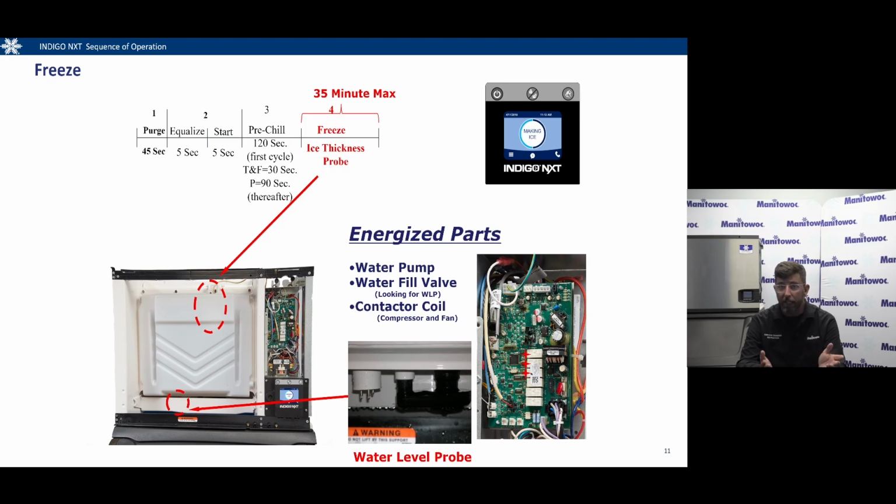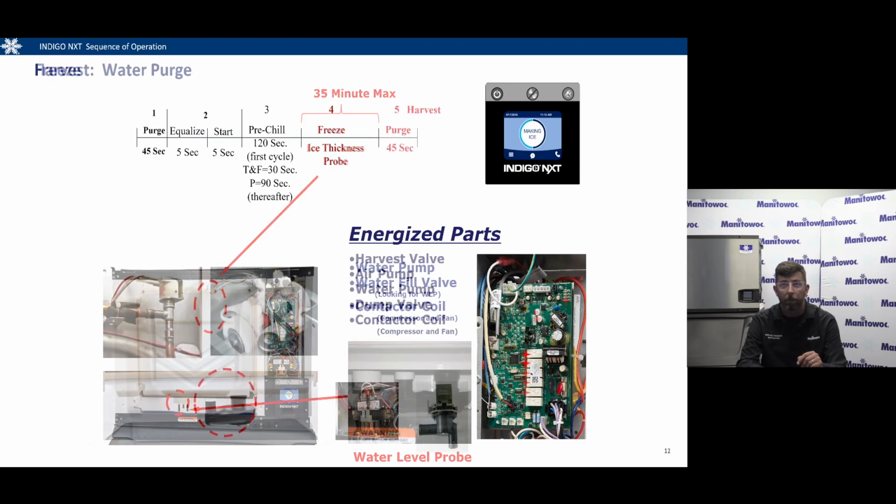Because you, as the technician with a display, can bypass it anytime you like. You can go into the menu, go to service, go to manual harvest, and initiate a manual harvest yourself. On the Cool Air line, on the Neo Undercounter, and on all the old Manitowocs, we do bypass the 6-minute lock-in freeze on the first sequence from an off state. That's there for troubleshooting purposes and because they do not have an option to initiate a manual harvest.